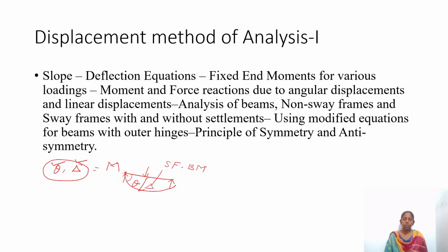So what are the parameters related to this in a force coordinate? If you apply a force, there will be a response of delta. If you apply a moment, there will be a response of rotation. You should be very clear about this. If you apply a force, there will be a deflection. If you apply a moment, there will be a rotation.